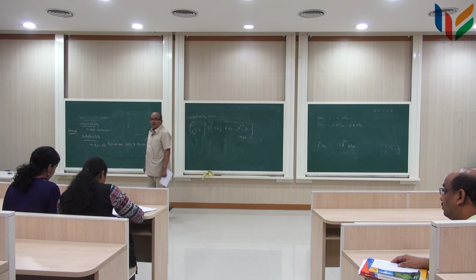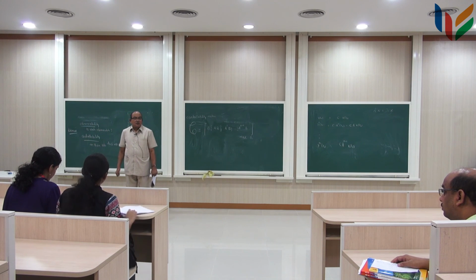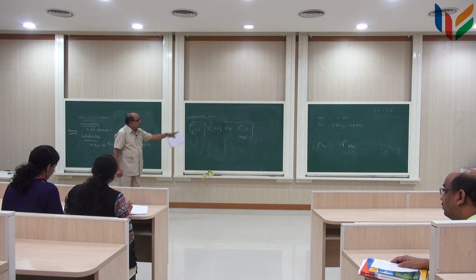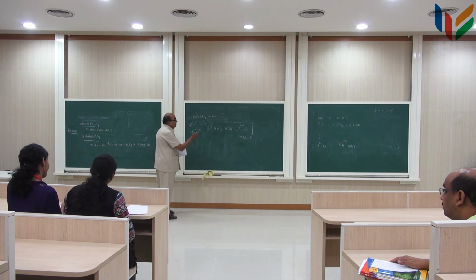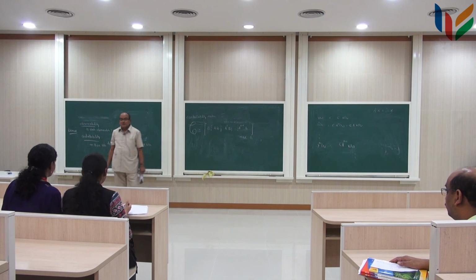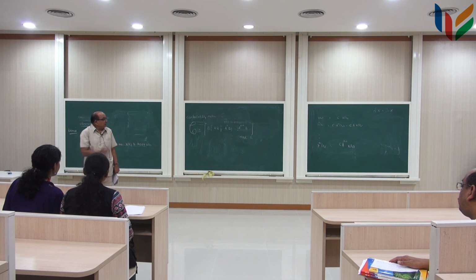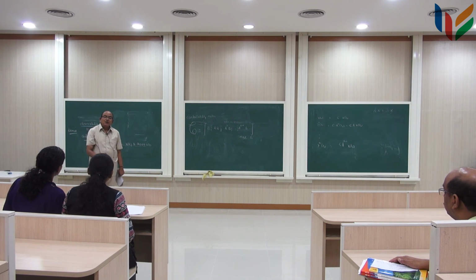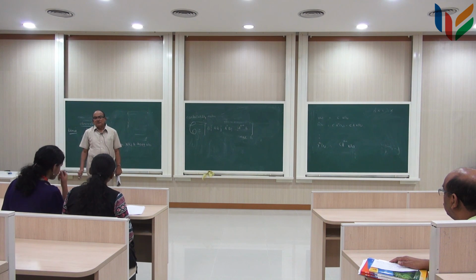This is also a rectangular matrix, and you can write down how much is the size of this. If this is satisfied, then you can find a set of u(t)s which will move x of t0 to the desired value of x of t. So, this is known as the controllability matrix.